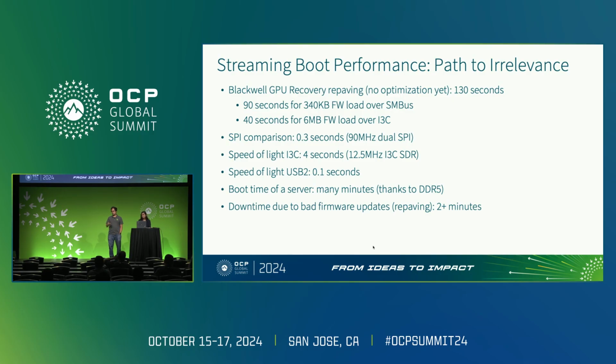What we wanted to do is avoid those problems entirely by leveraging fabrics that already exist across the whole platform, namely the out-of-band manageability fabric. The reference platform today would not have SPI from every device going out to some platform root of trust. Instead, let's leverage a fabric that already exists. The other nice part about I3C and MCTP is that these are fabrics that tolerate loss. And so it can make these protocols a bit more resilient as they scale to larger and larger platforms.